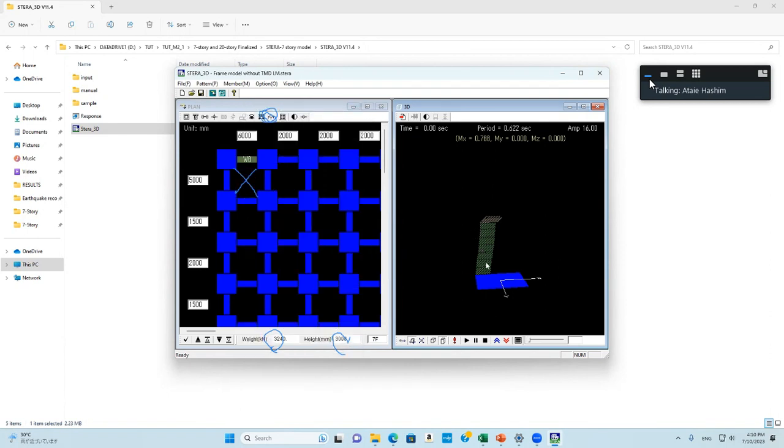Okay, Sensei. Is the stiffness of that floor the same as the stiffness of the frame model? No, it's not the same. The frame is a little bit stiffer. It's simplified to linear, so the lumped-mass model's natural period is a little bit longer. Okay, Sensei. I will try. If I have a question, maybe I will take an appointment through email.